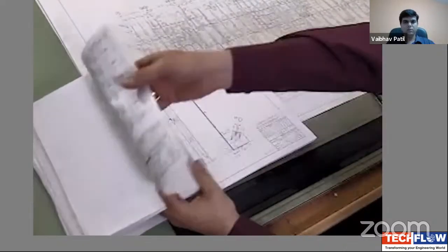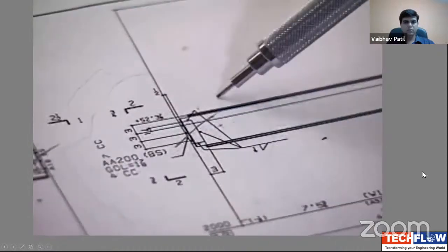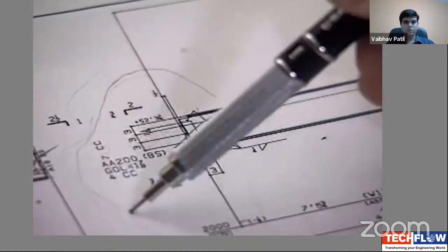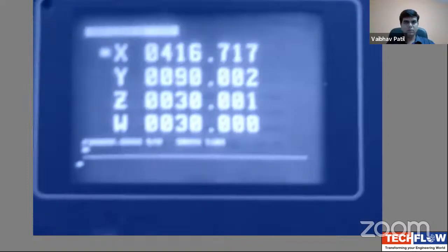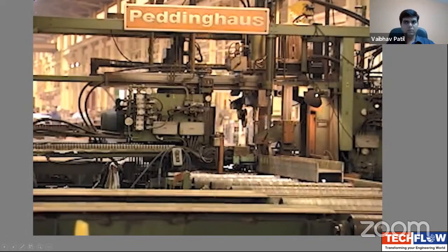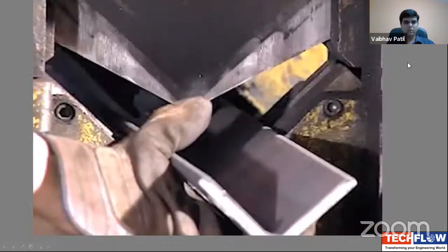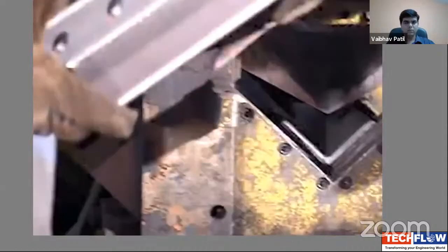In addition, if a member has been changed on the shop drawing, the detailer must also change the erection drawings that will be used in the field. All this information is developed with the help of computers, and it can be downloaded to the drill line in the shop or to the angle master to show them how to drill holes for the angles.